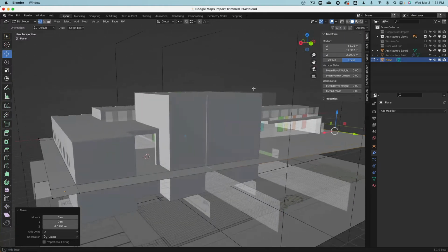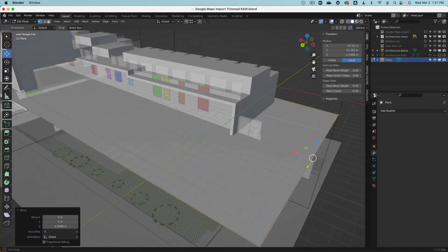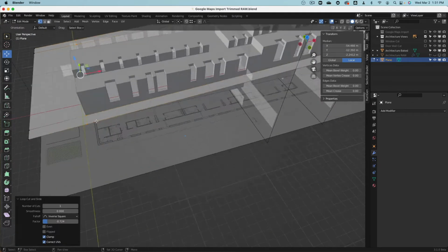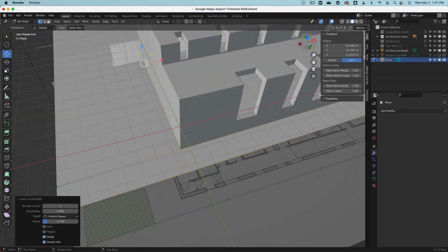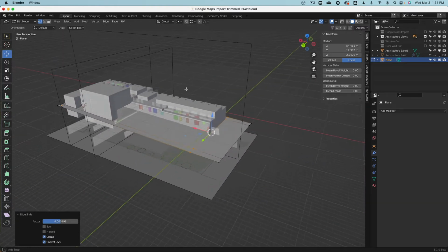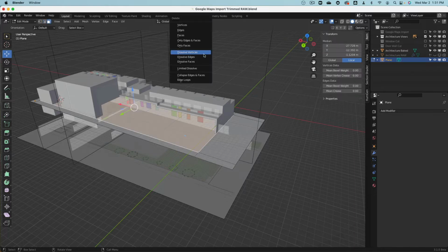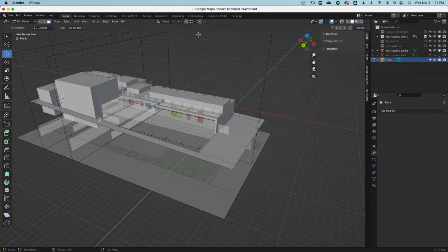Okay. Why did I actually create this line here? Check this out. When I press Control R on this edge and create a loop cut, I move this loop cut ideally really close, maybe in a top view, zoom in, and then GG. So not just G, but GG, which is for slide. I'm sliding this right to there. Okay, this is the easy, lazy trick. And then this face I can select, and if I want, maybe delete.